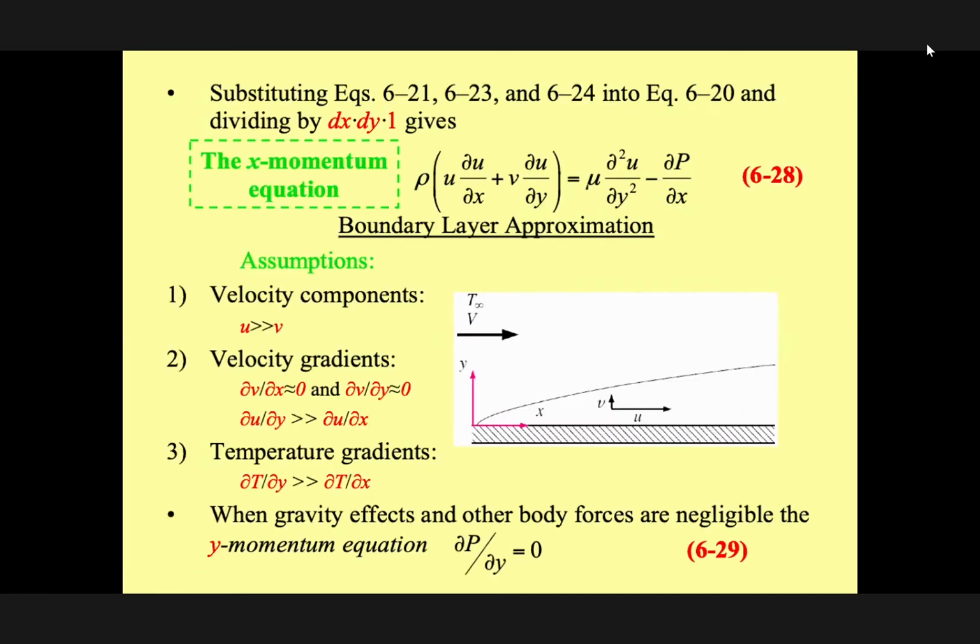Therefore, if we put all of the equations together, we end up with this equation. This is your momentum equation. Simplified, as we mentioned, this represents acceleration. This is shear forces, and this is the pressure drop. We have dp over dx, that means the pressure changing as we move in the direction of x, okay? And here, shear on the surfaces that we have, okay?